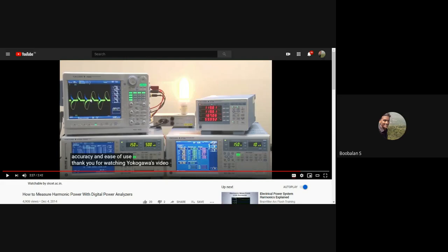So what happens in the electrical network if harmonics are present? People already study this. Due to harmonics, if you inject more and more harmonics into the electrical network, the conductor gets more heated. With more heat, the conductor connected to my distribution transformer means the transformer is also going to be affected. Wherever the temperature increases, definitely efficiency decreases.